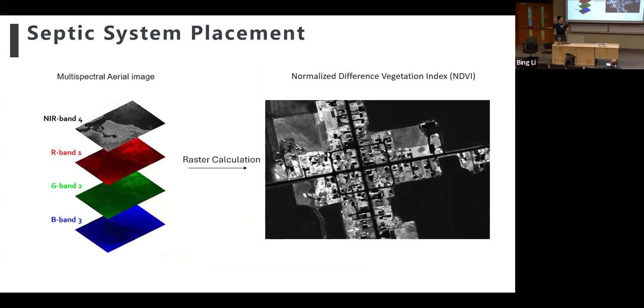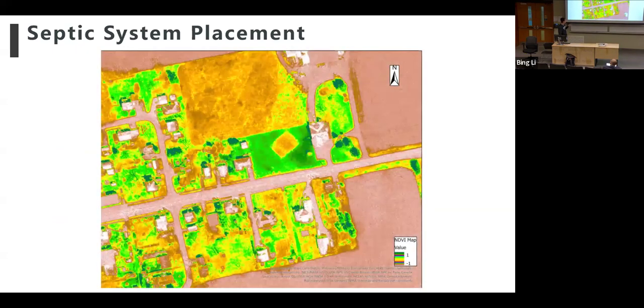So this variable is partly based on the NIR, the near infrared light. Since the light is very sensitive to green color, and we know all vegetation, the leaves, are green because they have chlorophyll A, by this feature we can identify the trees and the grass. You can see this is the colored map. The dark green ones would be the trees, this would be the grass, all these gray ones would be the bare ground, and those white ones are the buildings or some concrete structures.